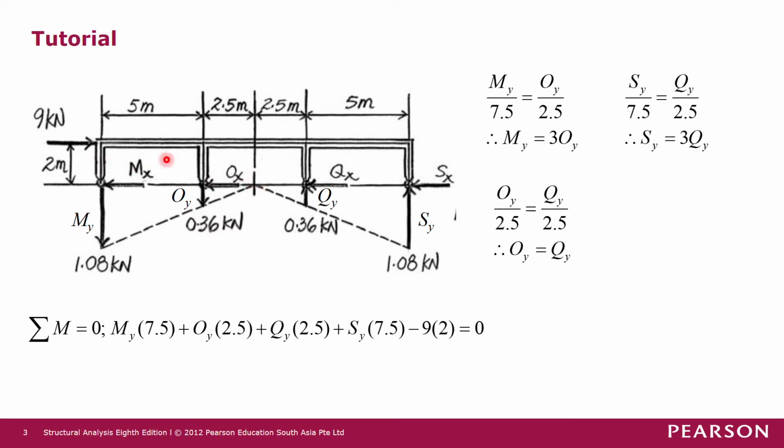We know that these columns have the same cross section. So the centroid of the group of columns will be at the center of the group of columns here. And we know that the stress or force in the column is proportional to the distance from the centroid. So we draw a line from the centroid slanting downward like that, and another line here slanting downward like that. The force in the columns on this side will be in tension, so we put an unknown tension force there. The columns on this side will be in compression, so we put in an unknown compression force for these columns there.